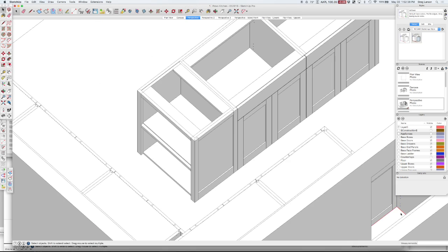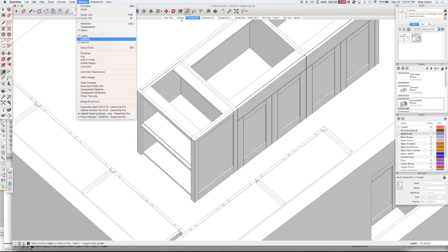And let's quickly run back to this drawing here, and we can see that if we're 15.5 for interior dimension, then I got an extra 1/2 inch to the wall, which is at 16, and then this 3/4 inch gap, which will be filled by the 3/4 inch side on the frameless cabinet. That puts us at a total depth of 16.75. So we need to remember that when we draw our cabinet.